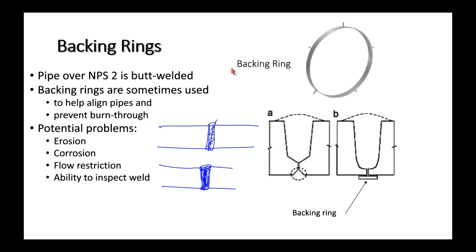You cannot use one of these. Illegal. If you do use one during your welding test, then you are limited to only using a backing ring. And no manufacturer, no pressure vessel builder, no piping fabricator hires guys who can only use backing rings. What they want is, can this person actually fill the root without burning through, without making globs of metal inside of the pipe, which we call grapes.